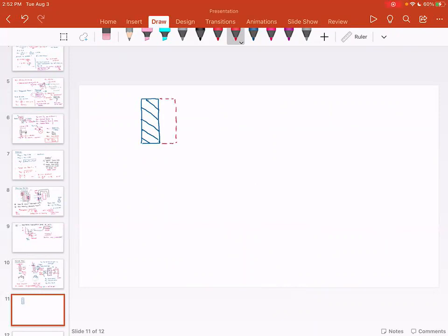So, this helical gear just has opposite helix, and this is called the double helical gear or the herringbone gear. What is the advantage or disadvantage of a double helical gear? As you can see, the left part of the helical gear will give you an axial thrust that will be compensated by the right side of the helical gear.